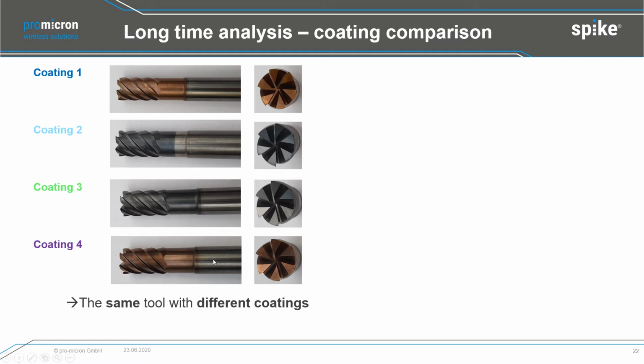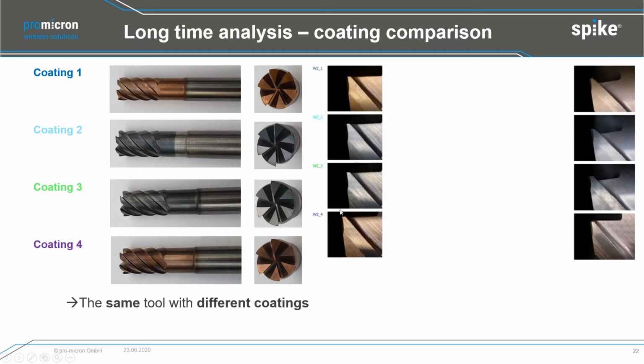He has 4 tools, different colors here, and he said, I'm doing a picture in the beginning of the tool, and I have defined that I need 100 operations in order to produce a little bit of tool wear, then I do a tool wear picture. And you can see here the purple one has the biggest wear, the green one has this corner in it, and it's getting really difficult between the 2 blue ones.